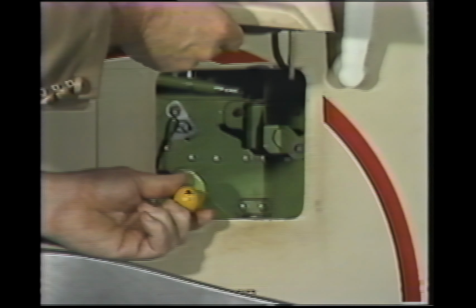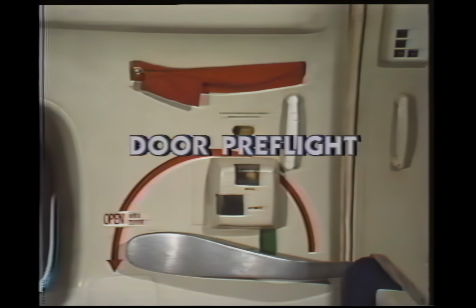Let's take a look at the manual door operation. With the mode selector handle pinned in the manual mode, rotate the door operating handle up and aft and push the door out until the door is in the open and locked position. There is a door safety strap at each flight attendant station located in a pouch in this compartment. If the door is open and a jetway is not in position, a door safety strap must be secured across the doorway.